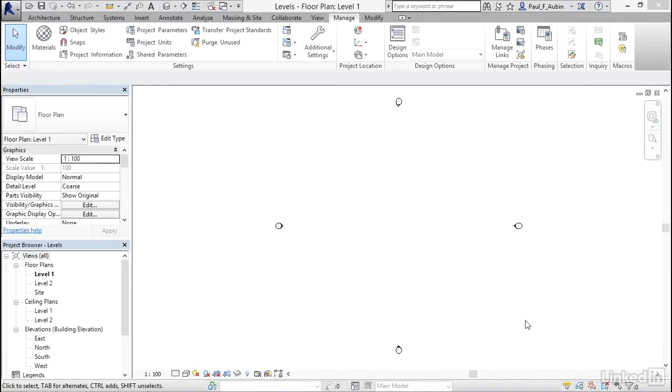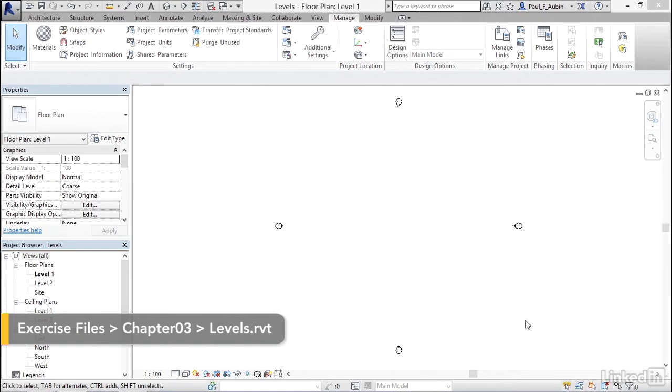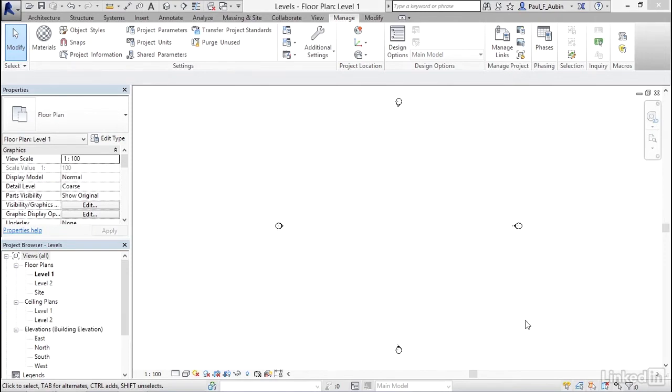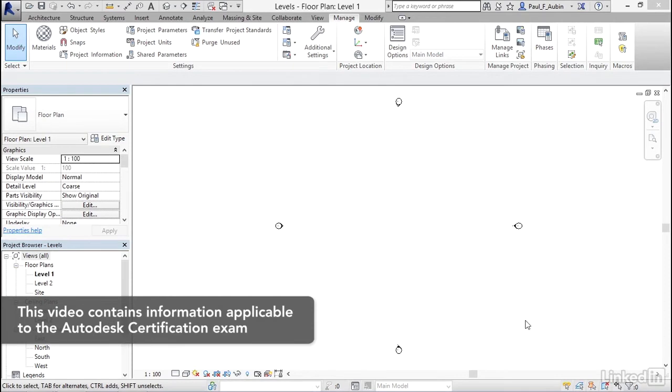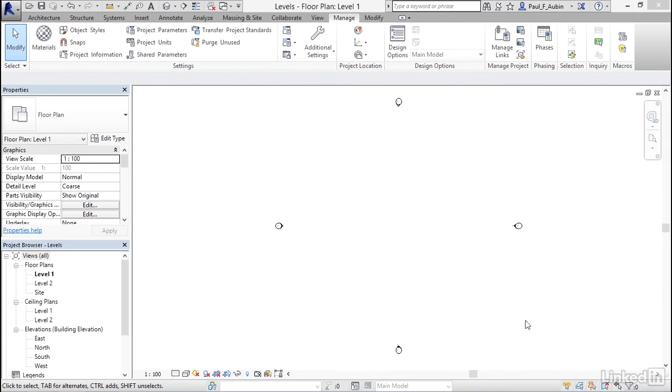Levels are one of the primary organizational and structural constructs in your Revit projects. They help determine where all the important heights are in your building. They can be in the positive or the negative direction, and then determine the important values in that Z direction. So it's very common to have a level at each story of the building. So I always tell people if there's a button on your elevator, you ought to have a level there.